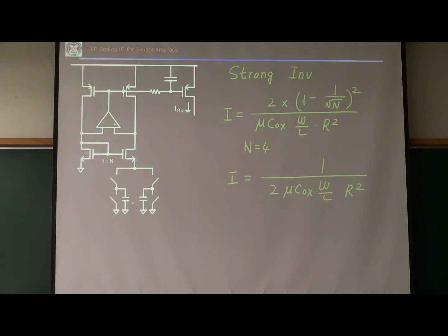In a switched capacitor, the resistance is just T over C. This is 1 over F clock times C. So I can substitute this here. My current equation is what? Let's use this one. Let's substitute my R there. Then what?